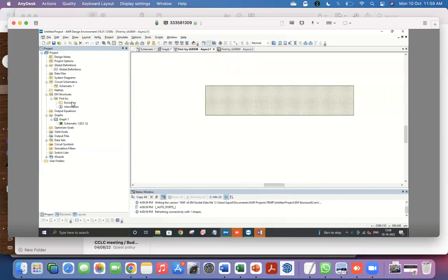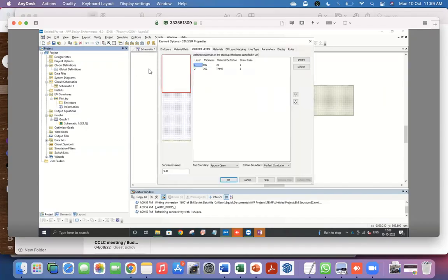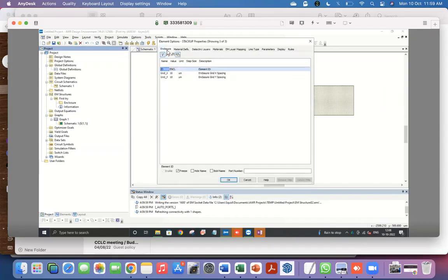One thing I forgot to mention is in the enclosure, in the main tab here, you have this grid spacing. This is sort of the resolution with which you can define the parameters, the dimensions on that particular grid. It's only loosely connected to the resolution of the simulation itself in terms of how it breaks things up.